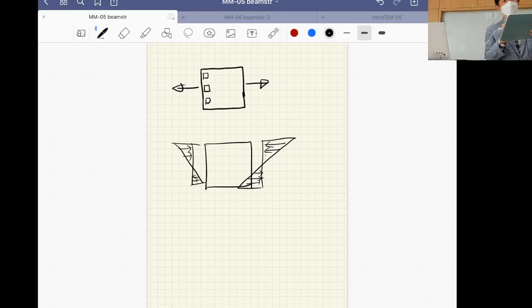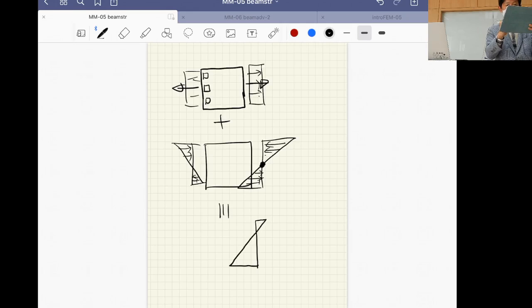Okay? So that's why if you superpose, so we have what? If you superpose, oh, by the way, the stress distribution from system 1 is constant. Then if you superpose these two, what happens is the origin of the stress distribution in system 2 is shifted toward the positive side. So for example, my stress distribution looks like this. Because of the contribution of this, we must have less negative stress part and more positive stress part. Is it clear? Okay, so the overall behavior is shifted to the positive stress scale.